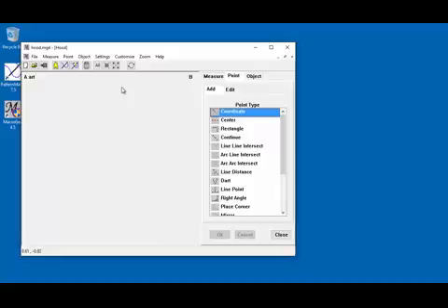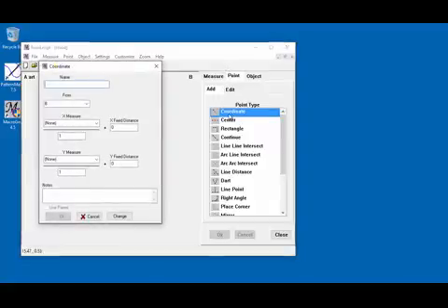Let's create a third point, which we will call C. So it's going to be a coordinate point, add coordinate, and we're going to call it C. It's measured from point B in a vertical direction. That's Y instead of X. We're going to give it a scale factor of -1, which will mean that the direction of measurement is reversed. It's down instead of up. So that's Y measure, and we want it height, and we're going to scale it by -1.